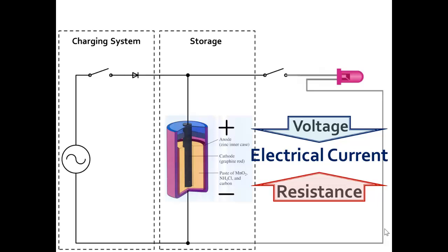Now if the switches are open, that is an infinite amount of resistance. There's going to be absolutely zero current flow, electron flow, through an open switch, because electrons cannot jump across the air. Now that's not totally true, and I will show you in a minute what I mean by that. But for the voltage that's supplied by this cell, when fully charged, gives you about 1.5 volts, so 1.5 volts. At 1.5 volts, that's not enough pressure to make electrons jump across the air gap of an open switch.